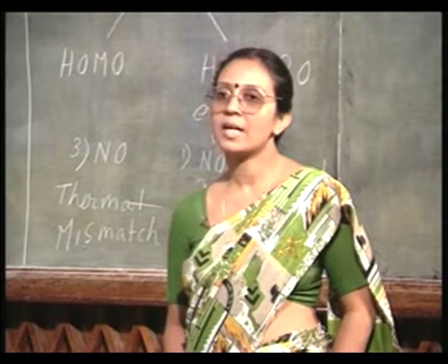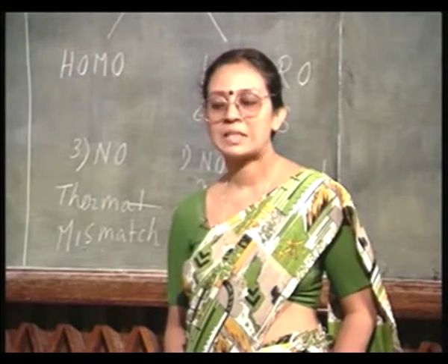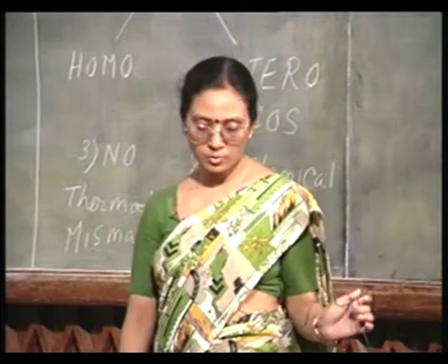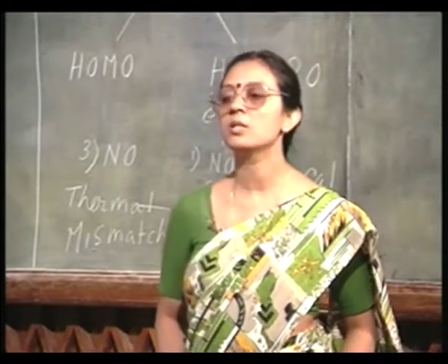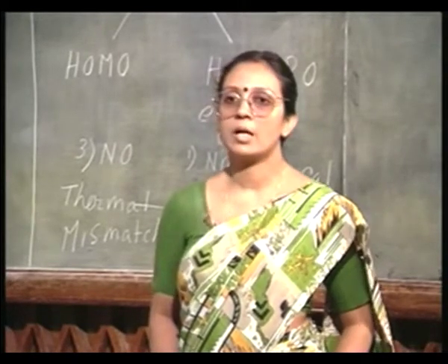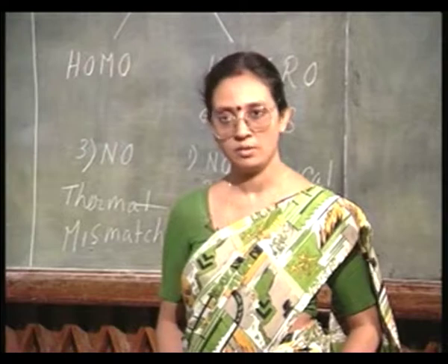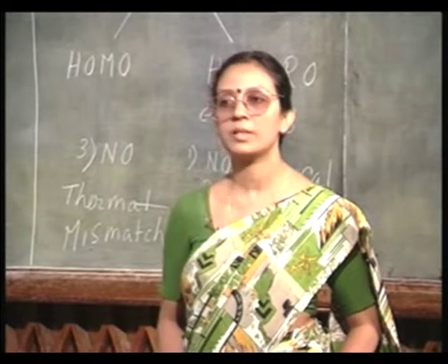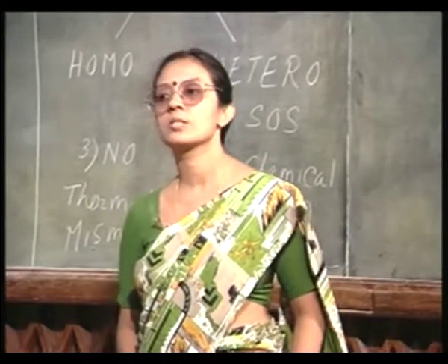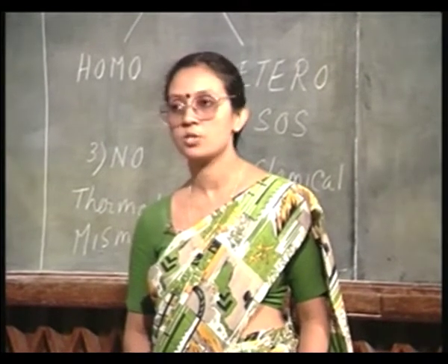Okay. So, strained layer epitaxy is a very important phenomenon today, which is however outside the scope of our present discussion, but let me just digress a little bit and tell you. Actually this heteroepitaxy is particularly useful when we talk about compound semiconductor technology. Because there you want to have so many things like aluminum gallium arsenide on gallium arsenide. In this case, of course, you have perfect lattice matching. Aluminum gallium arsenide is perfectly lattice matched with gallium arsenide. But suppose you want some other material like indium gallium arsenide on gallium arsenide, there is no lattice matching. So, there has to be a strained layer.